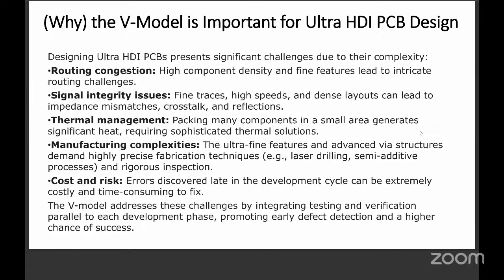Manufacturing complexities: I told earlier it is laser drilling and semi-additive, and a lot of leading OSATs and PCB companies have got their own secret sauces which they are not putting in the open. One assembly house can do it and another assembly house cannot replicate. Maybe the same company, a different branch in some other city, it becomes some sort of a secret sauce.